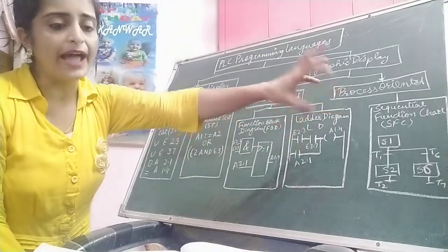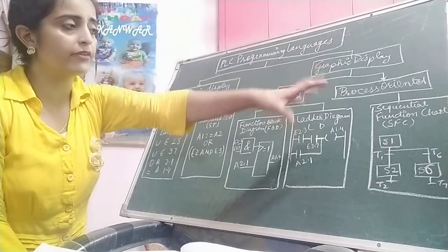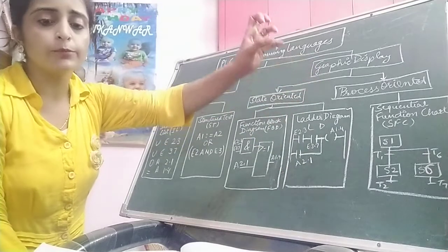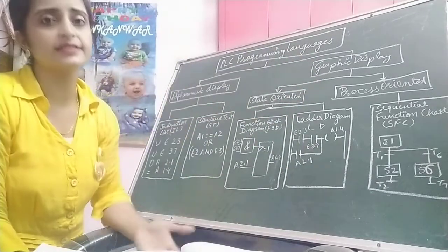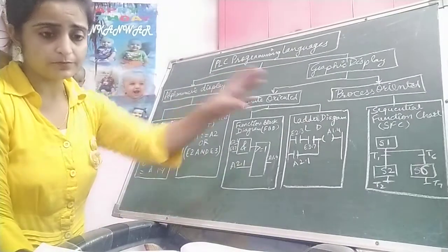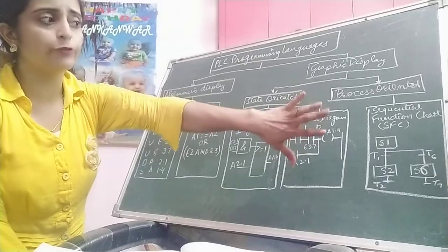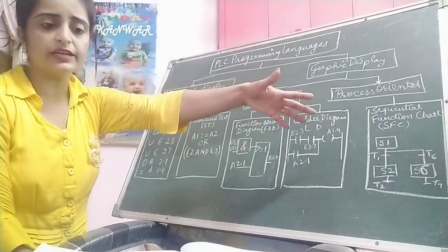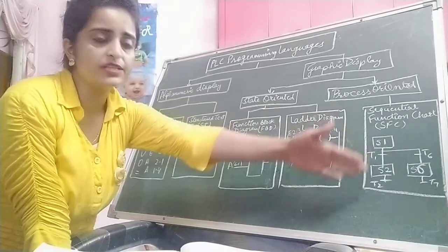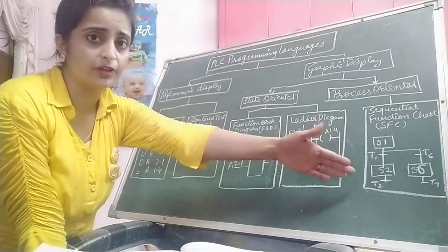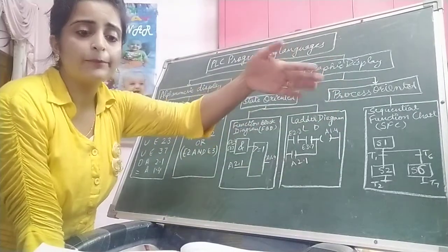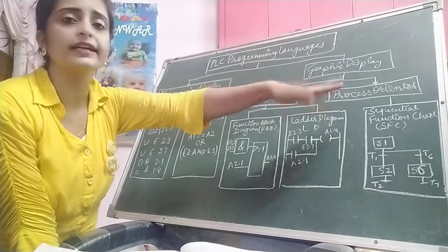It is a high level graphical programming language that is developed to accommodate programming of more advanced systems. It is similar to a flow chart, a pictorial representation of the sequence of events involved. Here you can see the sequence of events involved in this process, and the process is described by a number of separate sequentially connected states or steps.